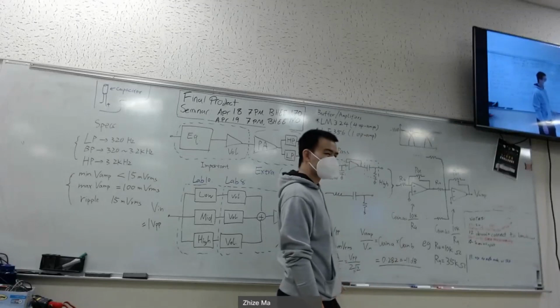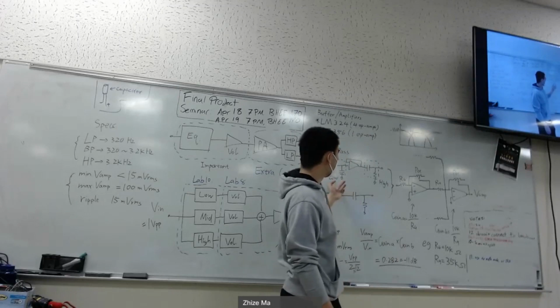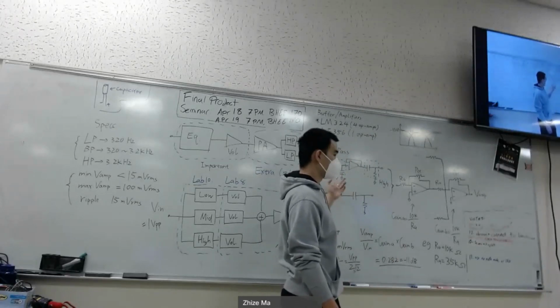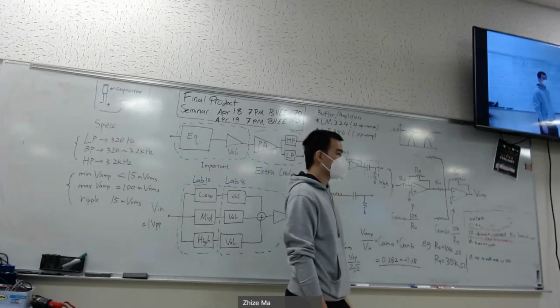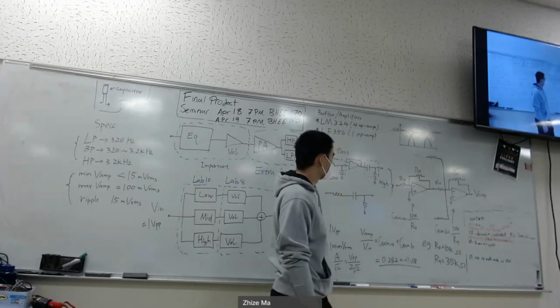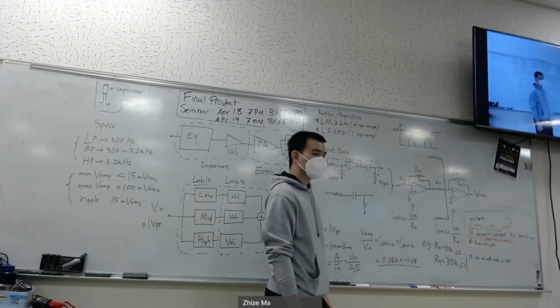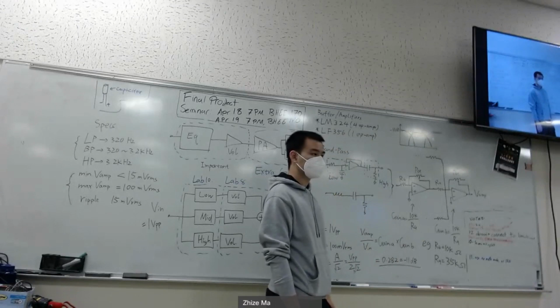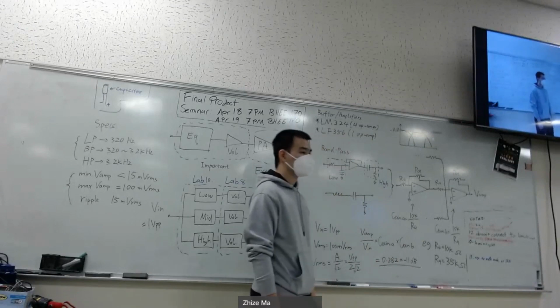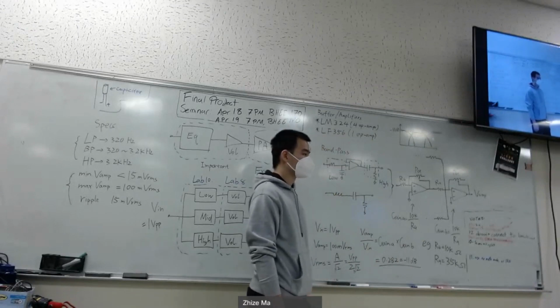I think one of the reasons could be the order of the high pass and low pass also probably matters. It also depends on the op amp, because essentially you're first doing the low pass filter, right? But then you're trying to get a band of that, but you already just lopped off everything after, say, 320 hertz, right?